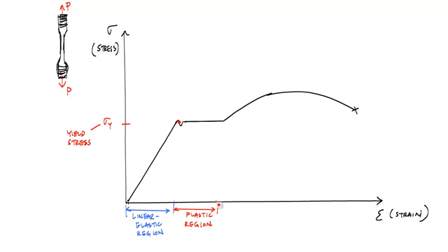Then it seems like the material gets tougher or harder all of a sudden, outside of this plastic region, and somehow it's able to start taking more load again, and the load increases, thus the stress increases, until you reach a peak way over here, some peak value, which we'll put boom right here, the maximum or highest point on this curve. This is the ultimate tensile strength, and people call this region up to the ultimate tensile strength the strain hardening region.